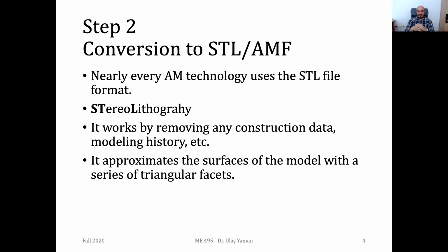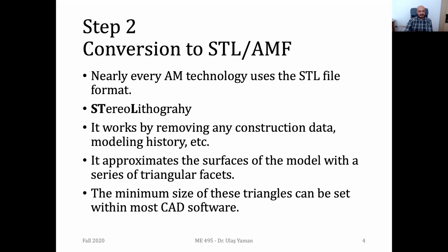This is the biggest problem with the STL file format. And we have triangles on the outer surface, and if you have, let's say, conformal surfaces, we cannot model them with STL files. Since an STL file is an approximation, you need to represent the same surface with triangles. So it's another problem of using STL files.